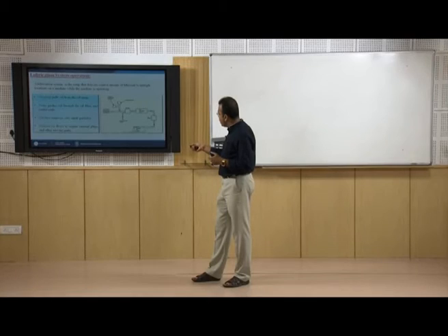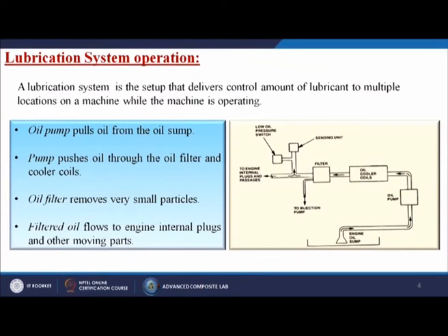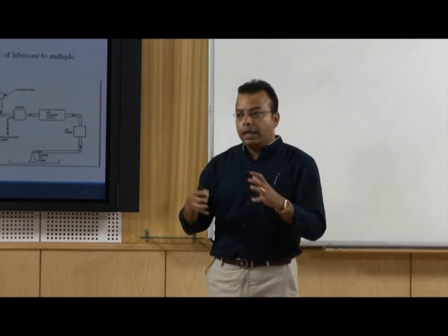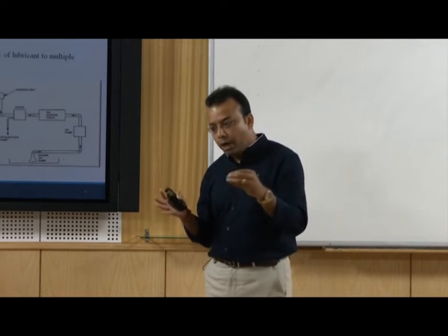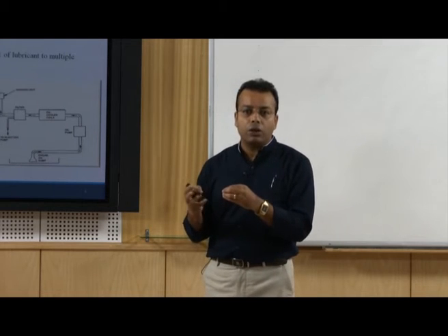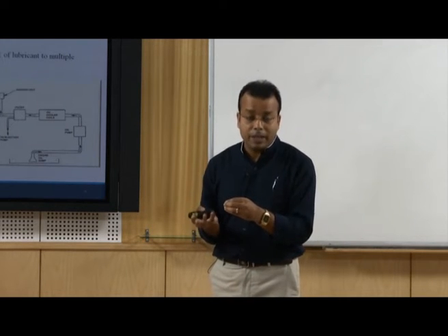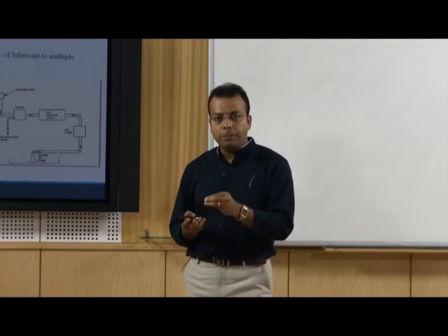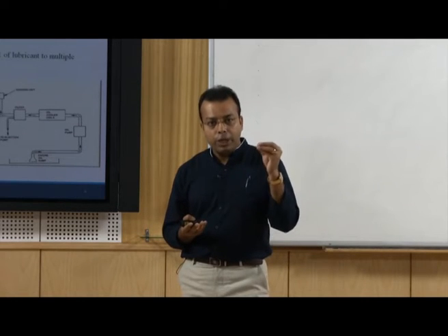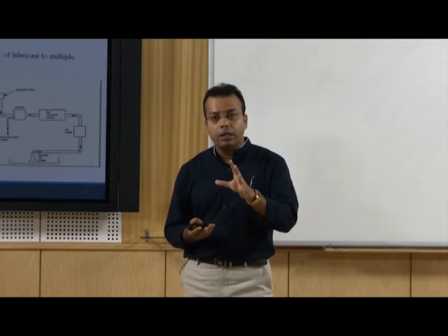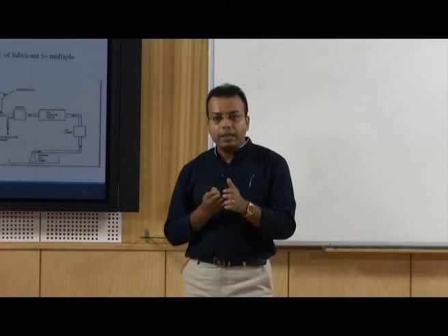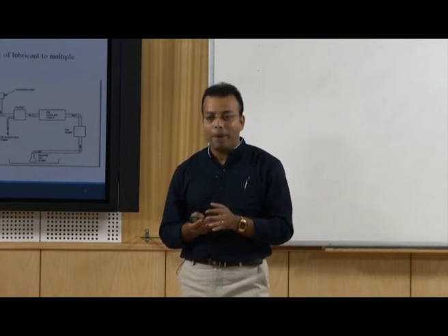Here we have an engine oil sump, where we store our lubrication oil. Then through a pump we take out that oil, and it passes through a strainer. If there is any dirt, particles, or wear debris present, it can be strained out of the oil itself. Then, for the fresh oil, we apply another pump which generates pressure, so that it can reach all the corners of the bearings or machines where there is relative motion between the parts.